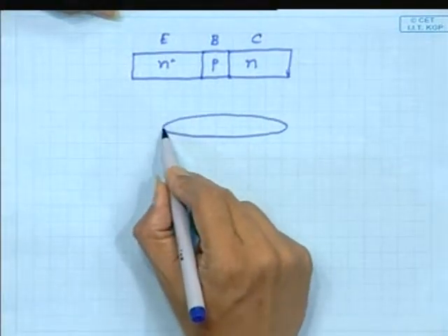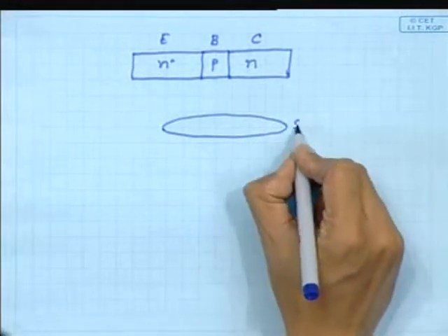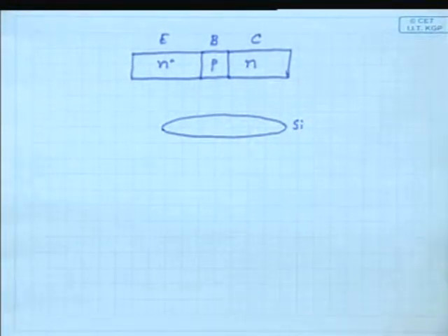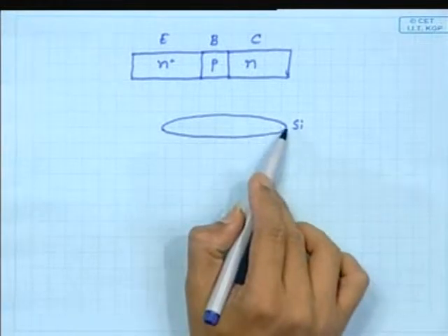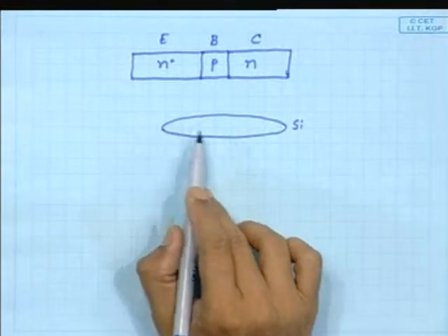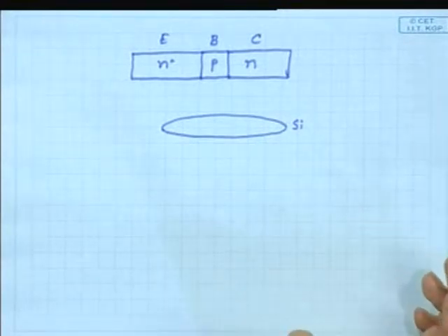say we start with a circular disc of very pure silicon. Very pure means electronically pure, I think you are aware of how pure it should be, because otherwise, if contaminants are there, you will not be able to achieve the required or desired electrical property. On that circular lamina, it depends on the technology actually, it might be as small as 2.5 inch in diameter or as large as 8 inch in diameter.